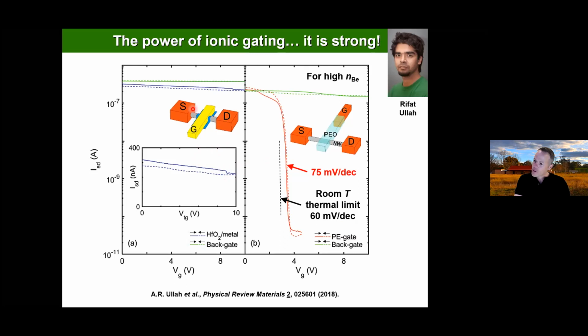If you take a nanowire transistor and try to use a conventional metal oxide gate on it, if you've got a very high doping in that channel, the current is very, very good. You drive your gate out to try and switch this off, and the gate doesn't do very much. If you do sort of an undergraduate device physics course, you learn very quickly that you can't make transistors out of metals because the voltage you need to deplete a metal is so high that your oxide breaks down. And sure enough, that's exactly what happens here. So if we drive this gate out to sort of 15 volts or so, it breaks down before you can pinch off conduction in this highly doped nanowire.